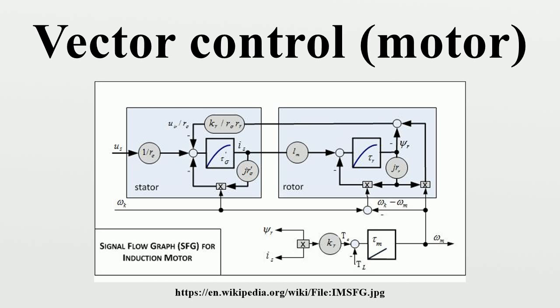It was originally developed for high-performance motor applications that are required to operate smoothly over the full speed range, generate full torque at zero speed, and have high dynamic performance including fast acceleration and deceleration. However, it is becoming increasingly attractive for lower performance applications as well due to FOC's motor size, cost and power consumption reduction superiority. It is expected that with increasing computational power of the microprocessors it will eventually nearly universally displace single variable scalar, volts per Hertz control.